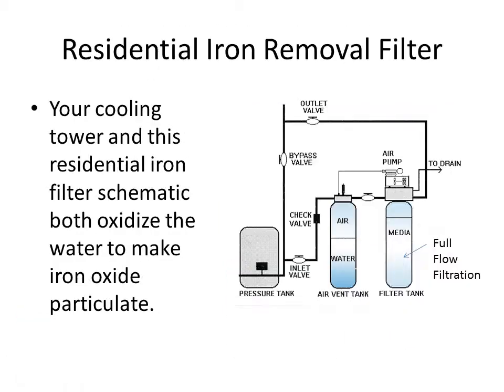Both this residential iron removal filter and your cooling tower oxidize the iron in the water into iron oxide particles. The residential system effectively removes this. Your cooling tower probably is not.